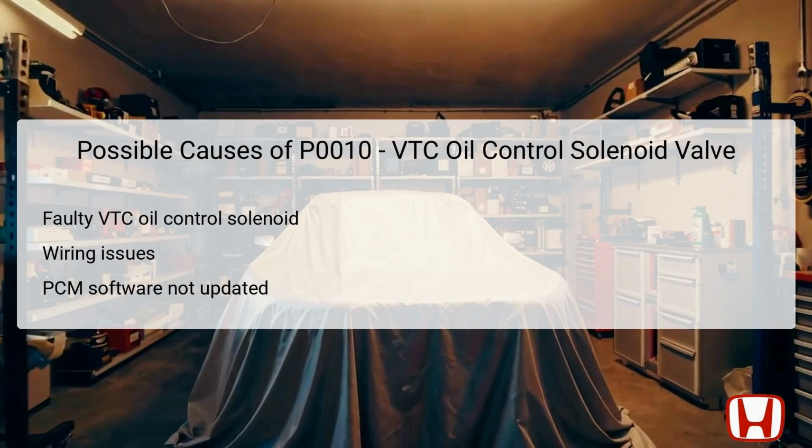A faulty VTC oil control solenoid valve is often the primary culprit. Its malfunction can hinder proper oil flow, leading to engine performance issues. Wiring issues, including open circuits or shorts between the valve and the powertrain control module, PCM, can also cause this diagnostic trouble code. Additionally, if the PCM software is not updated, it may not communicate effectively with engine components, resulting in false readings or erroneous codes. Each of these points necessitates thorough checks to ensure that both the solenoid and related wiring are in good working condition.